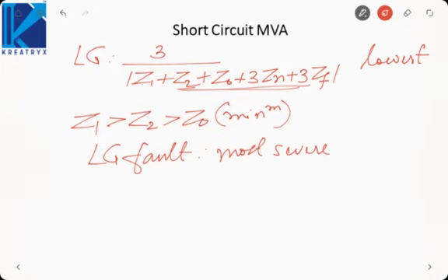So do remember this concept, so that if there is a statement that says that the triple line fault is the most severe fault, that is not universally true. It is false, because whenever the fault occurs at the generator, LG will be most severe.